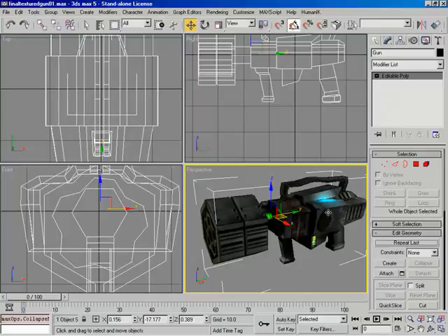And now our UVs have been folded over inside this editable poly, which is cool. That's what we want. And we've gotten rid of that modifier. In other words, we've gotten rid of history. Next thing I want to do is come in and grab sub-object elements, because when this gun was put together, remember we started out by modeling all of these pieces individually, then we attached them all together in the UV section. Well, the model itself, remember, is all of the different elements that were put together. So we can still select them.